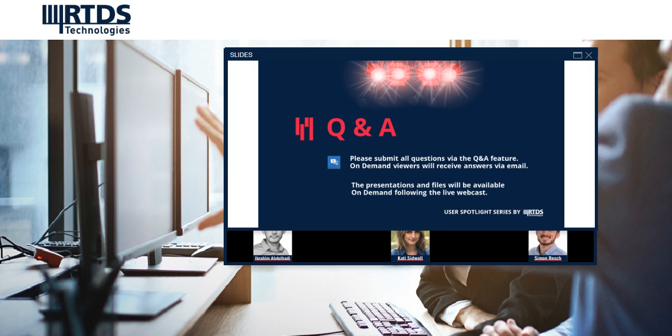So yes, as Ibrahim mentioned, one of the key elements of the work is to try to quantify the limit of the communication performance on the impact of the wide area monitoring and control system. So basically, we try to test the limit of how much data loss we can tolerate, and how much latency and jitter the system can tolerate, and then we try to use that to quantify the specification for supporting a wide area system, for enabling the control.